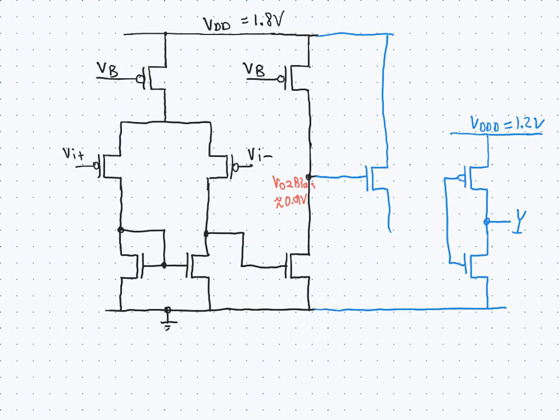We would need another bias transistor sitting in here with another bias voltage if we use a source follower, so VB2, in which case we would have the bias condition of this one here being around 0.4 volt, which is closer to the ideal level of 0.6 volt at the input there. But the detail of such a design really depends on the process and how to get from the analog side to the digital side if the power supplies are not the same.